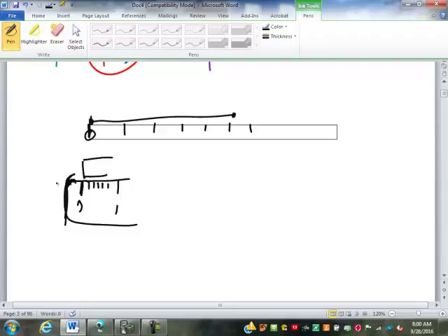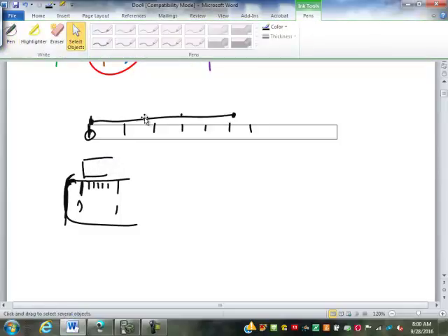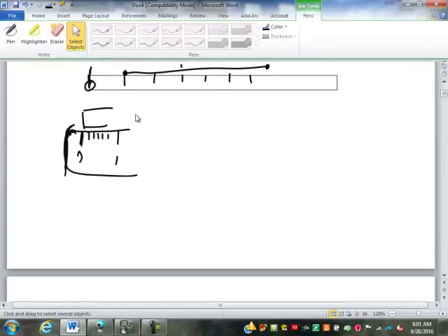That's why a lot of people say that rather than lining it up at the very beginning of the ruler, you should actually line it up with the 1, and then just subtract 1 from your measurement. I'm not going to make you do that, but for real precision measurement, sometimes that's a better way to do things. For really precise measurement, in a little while we're going to learn how to use calipers and micrometers, and that's the better way to do the really precise measurements.